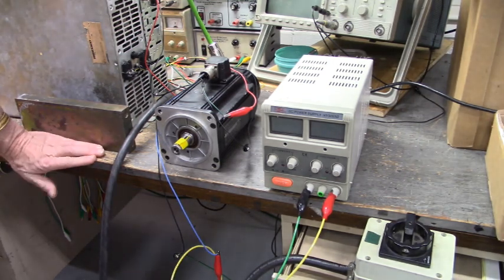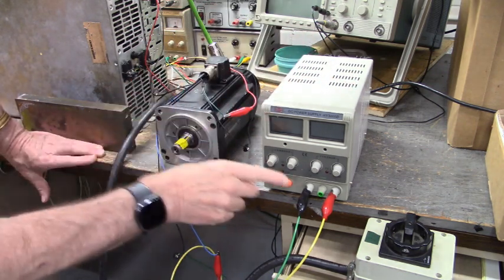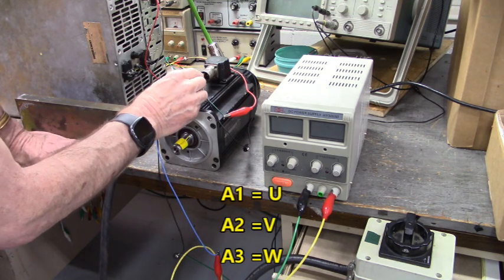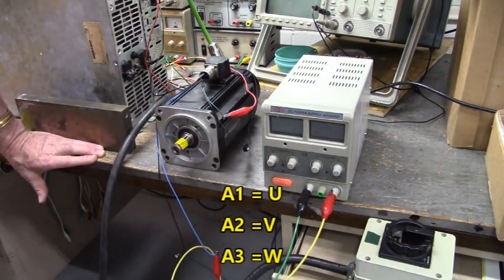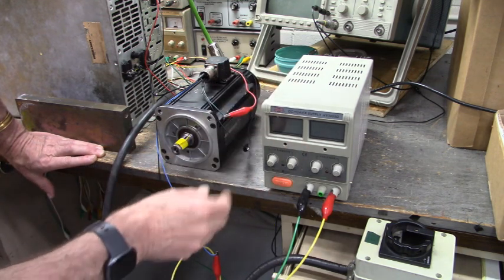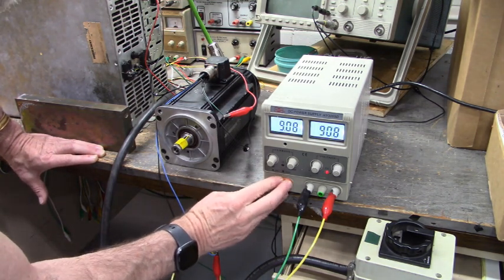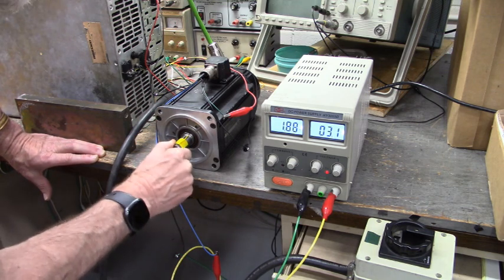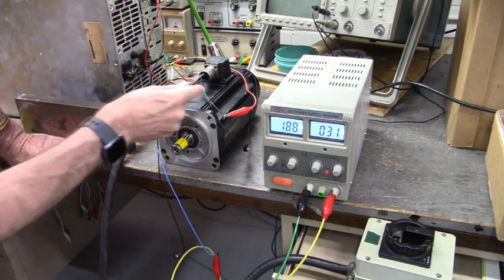Okay, now I have this power supply here, positive connected to A1 on the motor and A2. Now let's power up the drive. We're going to lock the rotor with this power supply. I got it set to 3 volts, about 3.3 volts DC. So let's turn this on. Now you can see that the shaft moved a little bit and it's locked. Now I have the brake released with the power supply up there, 24 volts DC going to the brake.